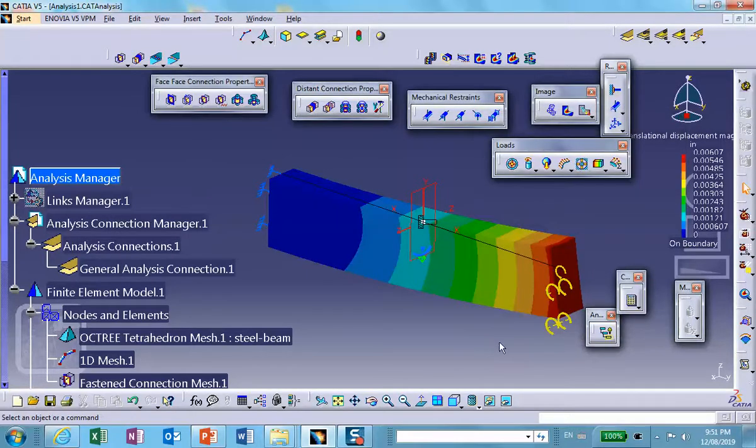I showed you the process. You may want to go to that paper and compare the finite element calculation in more detail with the area transformation method. And in that paper, we are also comparing it with the fully three-dimensional model. In other words, the top is modeled with solid elements, the aluminum is modeled with solid, and the seal is modeled with solid. And then you can see how different they are.